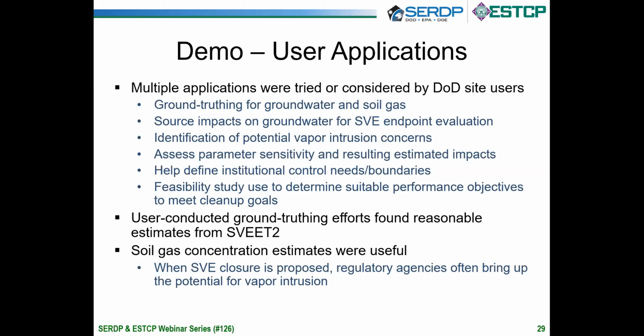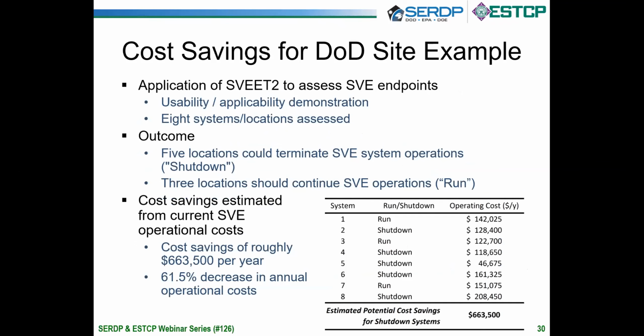And the soil concentration estimates were noted as being useful because when SVE closure is proposed, regulatory agencies often ask, well, what about vapor intrusion? So it's nice to have those soil gas estimates as well.